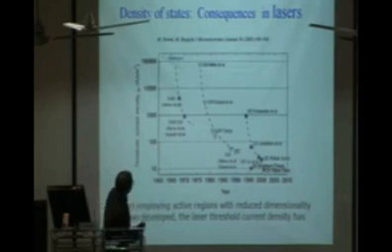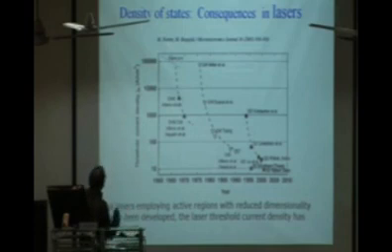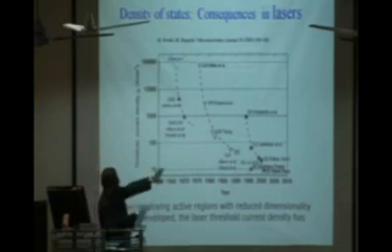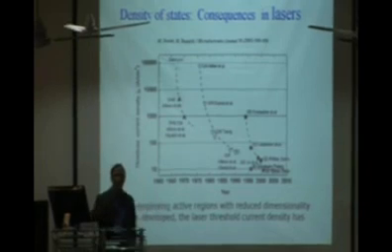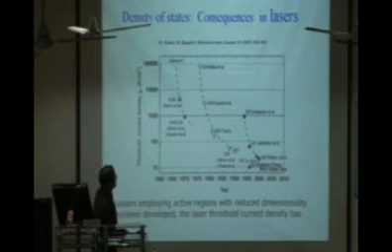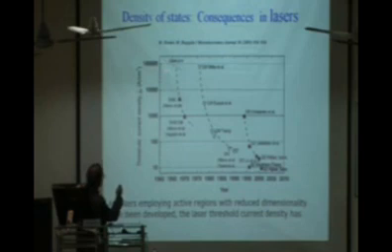We can put a similar roadmap for an optical system. In a laser, the most important figure of merit, or parameter, is the threshold current density. That means how much power I have to put into this laser so that I can get this lasing action to take place for the whole day or for the whole duration of the conference. And you see it initially starts with a typical gallium arsenide p-n junction of about a million ampere per centimeter square.